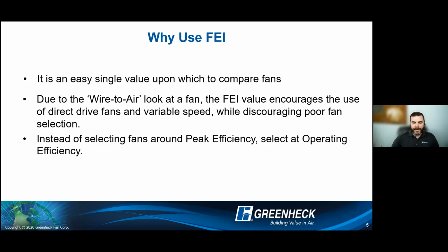In general, I can say that large fans are going to have a better FEI. If you have a large fan that moves slowly, you're going to have a better, more efficient selection. You're also going to have better sound characteristics with that larger fan. Now, if I go down 2 or 3 sizes, can I get that fan to do the same operation?